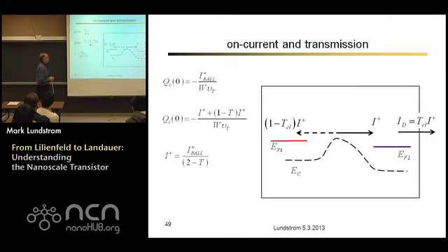Okay. Now, when I have scattering, I'm going to inject some fixed amount. I'm going to inject some amount I plus, and the key thing here now is that the key thing is MOS electrostatics. If I've designed my transistor properly, charge is Cox times (Vg minus Vt). It doesn't matter whether it's ballistic or whether it's diffusive. That's just electrostatics. So I equate the ballistic expression to the expression with scattering.